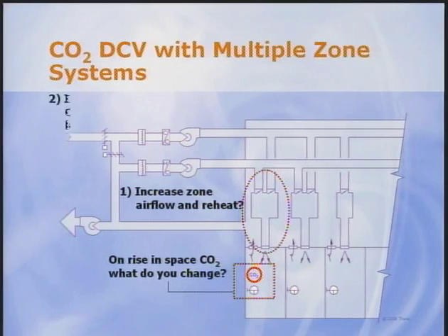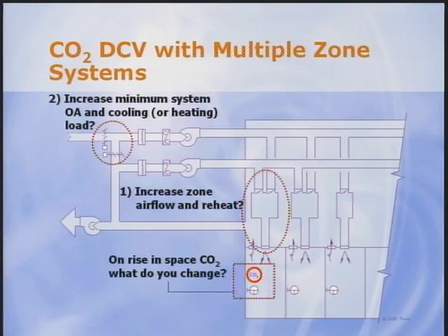Or we could increase the outdoor air minimum position, but this will increase outdoor air to all zones, not just this zone. If the outdoor air temperature is below the supply air temperature set point, this can increase heating energy. And if the outdoor air temperature is above the supply air temperature set point, this will increase cooling energy. So, which is the most energy efficient? We don't know yet exactly. That is part of the ASHRAE research project. But here's one approach that we do in our office.